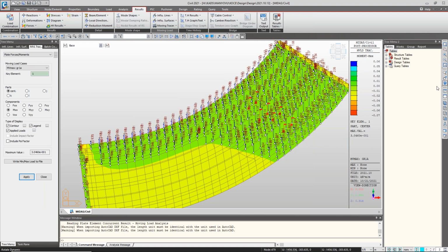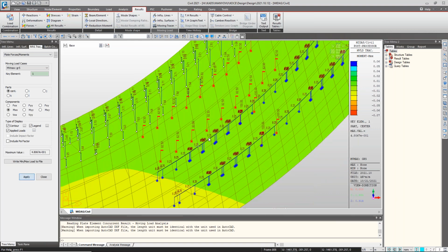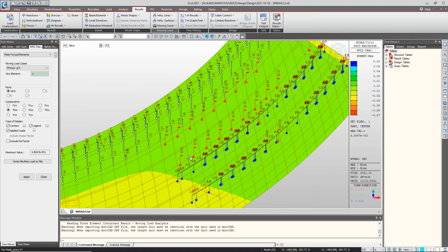And actually, when you go to group 5, which includes load model 3 plus load model 1, the software automatically picks it. You can see here, it has done a simulation of a straddling vehicle, and you can see the maximum force on that plate that we chose. Or this is plate 1, sorry. I had to choose plate, I think it was 385. So plate 385, I hope it's this one. Okay, so you can see that it accurately gets exactly what the code shows.